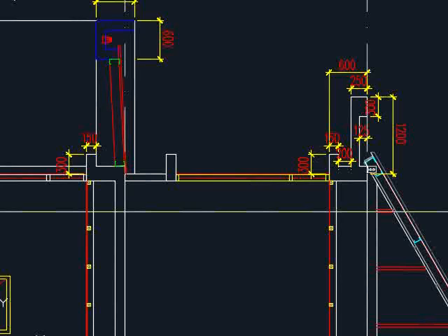The bottom line here is, when you design the beam here, you will consider a rectangular beam for the design. You might need to do some minor checks in terms of the torsional loads applied onto it. That means under torsion, your shear links will play a significant role.